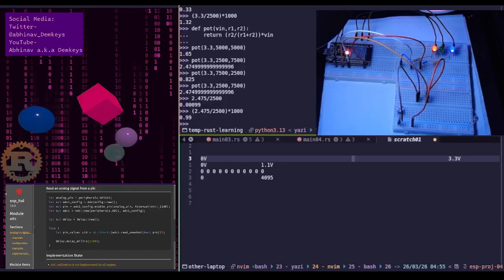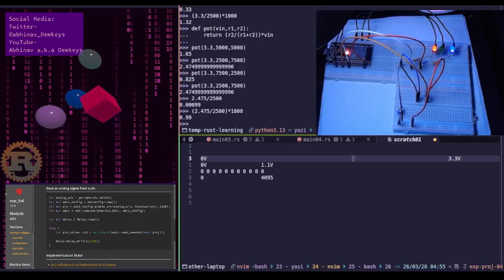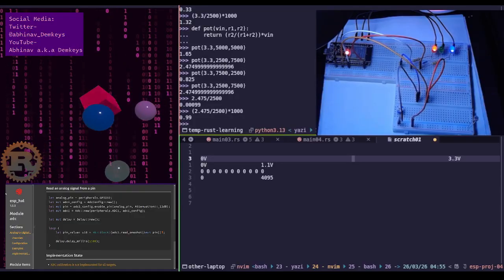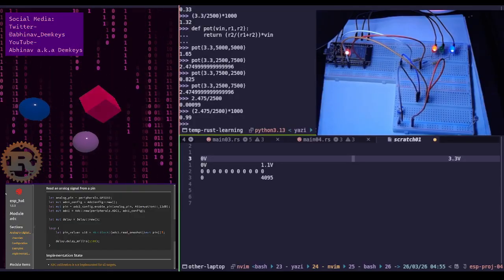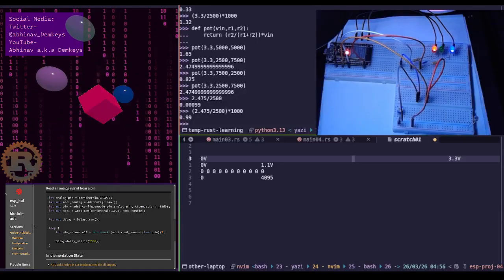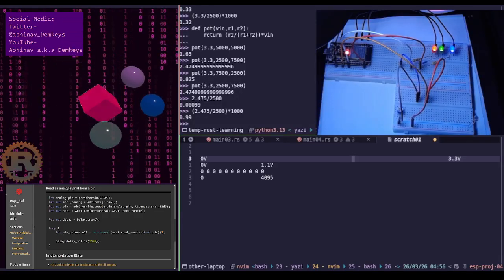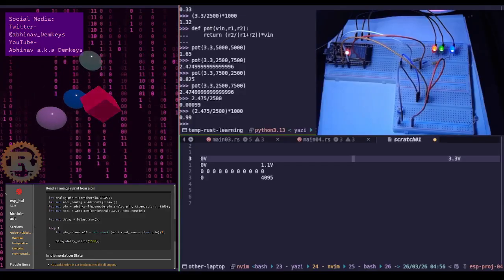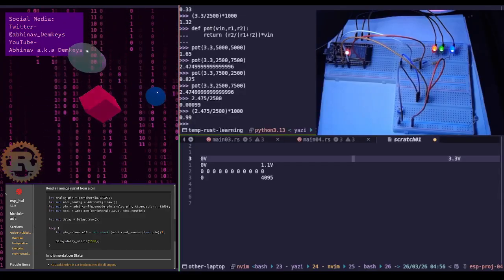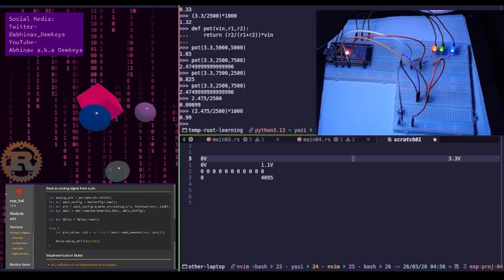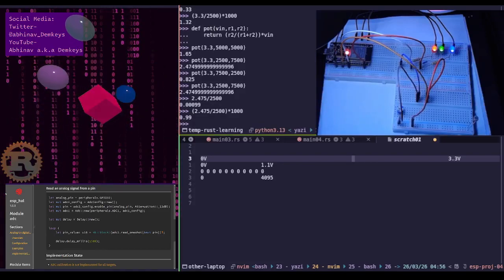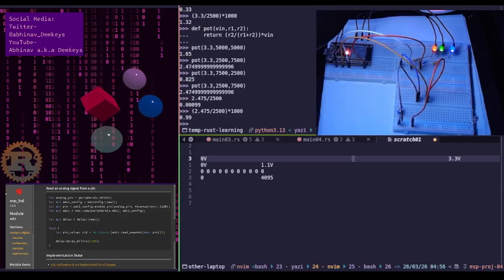Okay, if the resistance of your potentiometer is too high, for example using a 1 mega ohm pot instead of a 10K pot, the trickle of current isn't fast enough to charge the internal capacitor before the ADC takes its readings. Your 10K pot is perfect, the source impedance is low enough to charge the ADC's internal guts almost instantly.